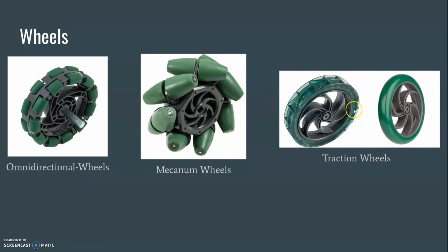So the VEX traction wheels are not typically useful for most types of chassis. The fluidity of driving with these wheels is much lower than that of the Omni wheels. They have a higher turning scrub, which is the force that is aimed to the side of the wheels when turning, and overall, turning scrub is bad.